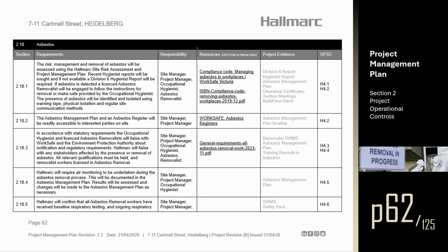Section 2.18.4. Hallmarc will require air monitoring to be undertaken during the asbestos removal process. This will be documented in the Asbestos Management Plan. Results will be assessed and changes will be made to the Asbestos Management Plan as necessary. Section 2.18.5. Hallmarc will confirm that all asbestos removal workers have received baseline respiratory testing and ongoing respiratory testing. This will be documented in the asbestos removalist SWMS or safety documentation.